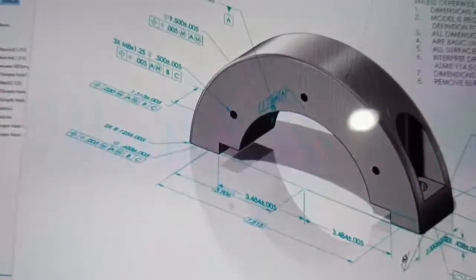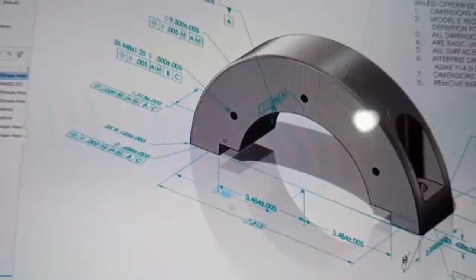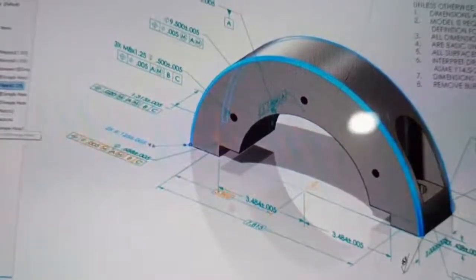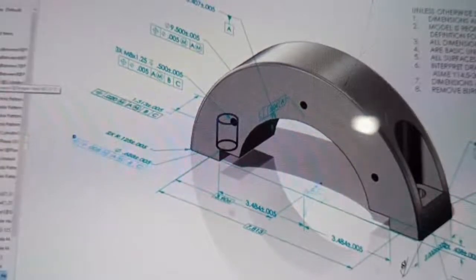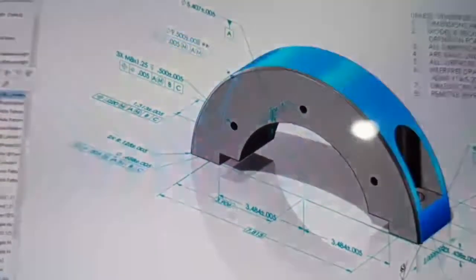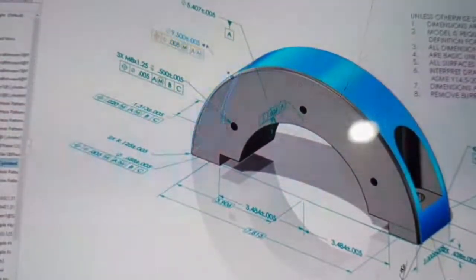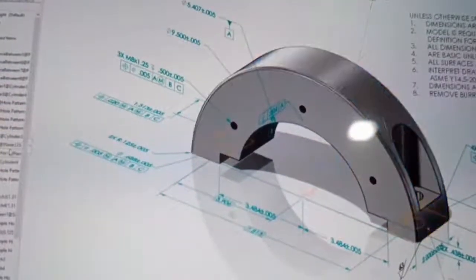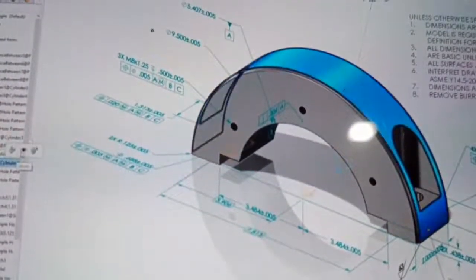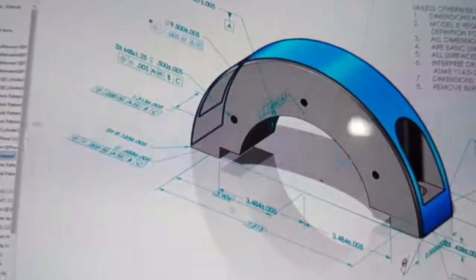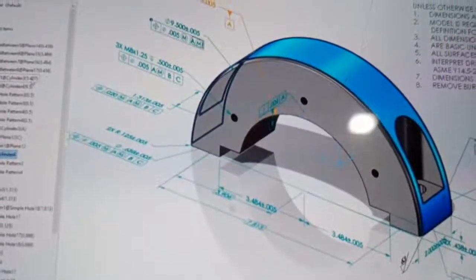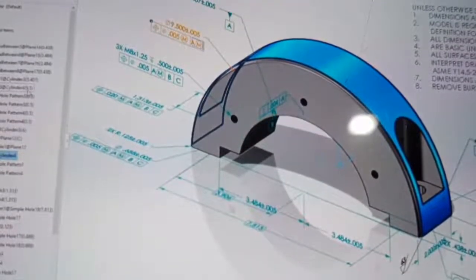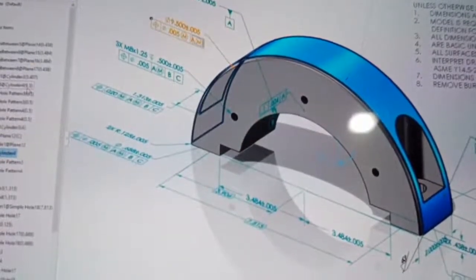In SolidWorks 2020, individual annotations are now listed under each annotation view to help visualize the relationship between annotations and the view to which they were assigned. When you select an annotation in the FeatureManager, it's highlighted in the graphics area, and annotations can now be easily hidden or shown. The names of the DimXpert annotations now follow a new format, which adds the feature name and dimension value to the previous format.